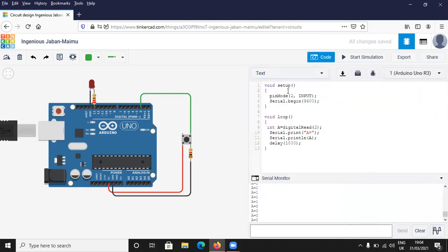Then now you go to the code. You need to do something about it. What are we supposed to do? We introduce the LED because it's a new device that we have added. We need to do that. So let's introduce the LED, the port to which you have connected it. So you copy, then you paste, and change this to 13. Then you have that as output.